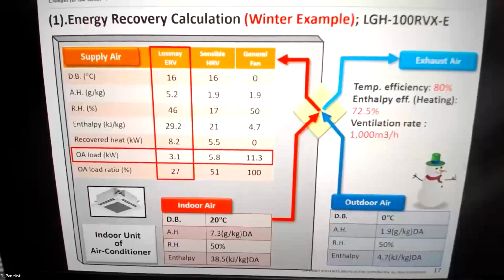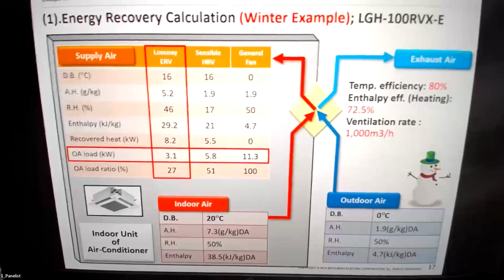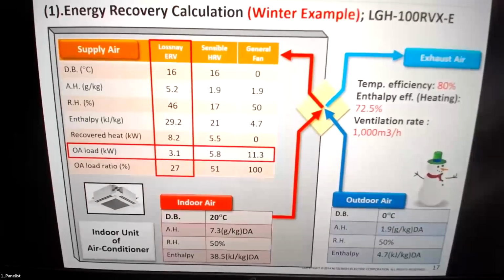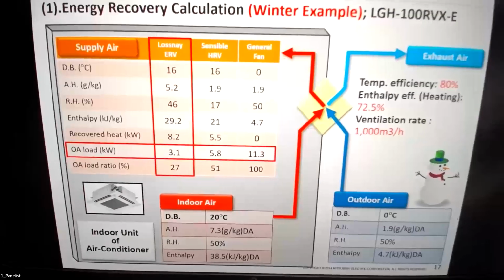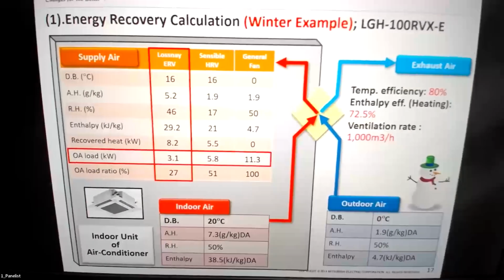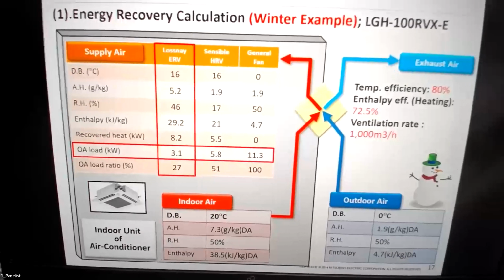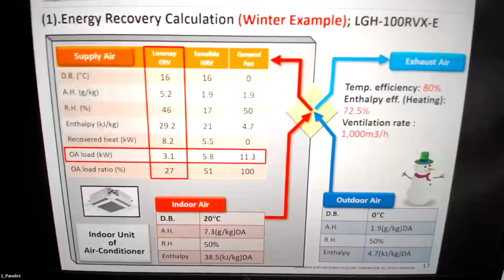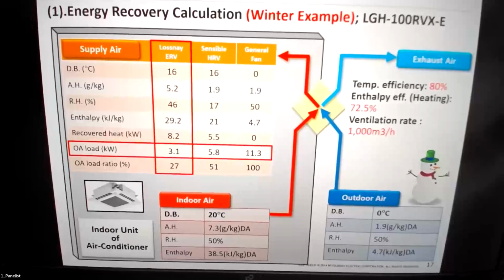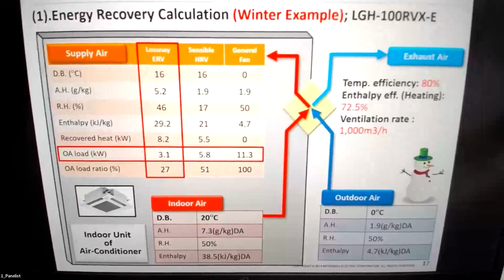Then would there be any reason why the material that you use for heat and moisture transfer can get polluted by some particular type of pollution? So the requirement is maybe that the supply is very, very clean, because particles, dust and so on can be deposited on it, which will reduce the characteristic of it and then the transfer of the moisture. Did you look at that aspect as well?